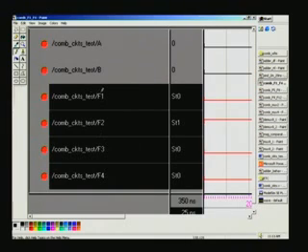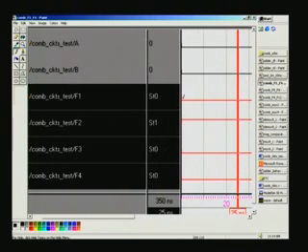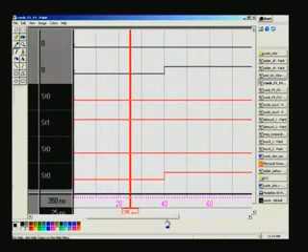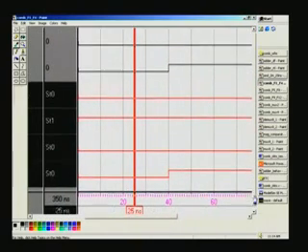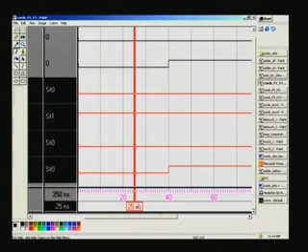Remember that F1 is nothing more than a buffer. So a buffer of the A signal. Whatever is the A signal, you should get in F1, and F2 is just the inverted signal of A. So let us just remember these two and see. The third column is F1 and F2 is the fourth one. First two are the A and B inputs. So just remember here, and once again the time element is there. And if you remember, we have given 25 nanoseconds at one point of time. That is what is marked there, but it's not of much concern right now.